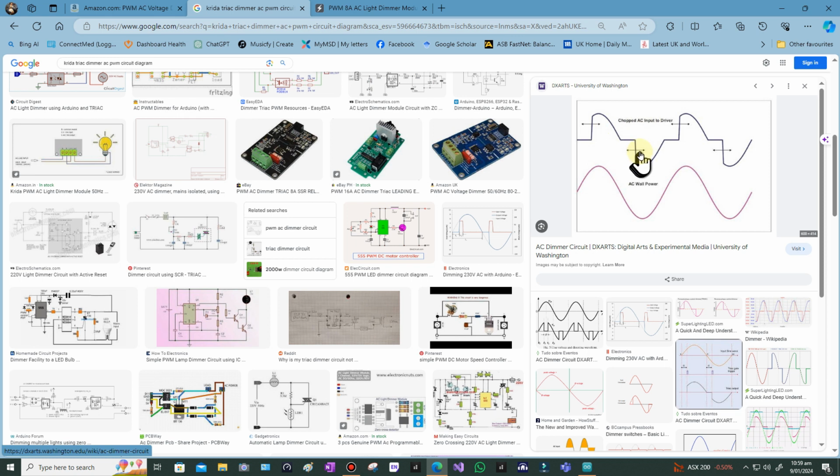Well, we did do triacs, but I can't remember doing the calculations. So triacs are used to control the power to devices, like incandescent bulbs or inductive loads. When you've got inductive loads, you've got to be careful because they can give rise to spikes in the triacs. But snubbers, just an RC network across the device, are supposed to reduce this, although it does have side effects as well. This board has got built-in snubbers, and although I haven't tested it on an inductive load, I've read some good things about it.